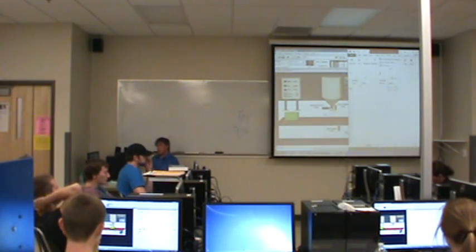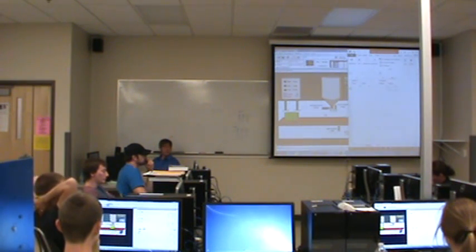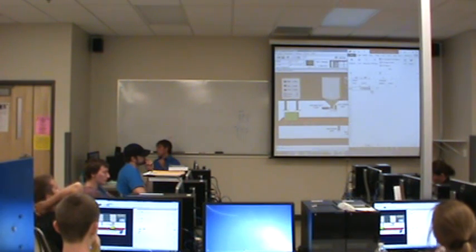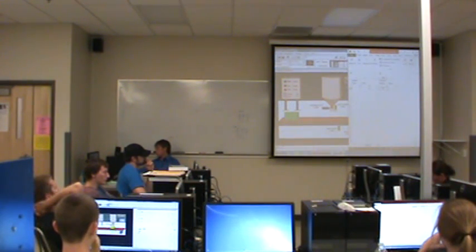Well, in the mechanical system, what's going to happen after a long period of time is that the level will not be true, but prox will be true because the box will come into place. So prox true, level not true is the next set of inputs that we're looking for. That's the next step in our sequence. When that happens, what do we want to do? We want to turn the motor off and turn the valve on because we have a box in place that's empty that needs to be filled.